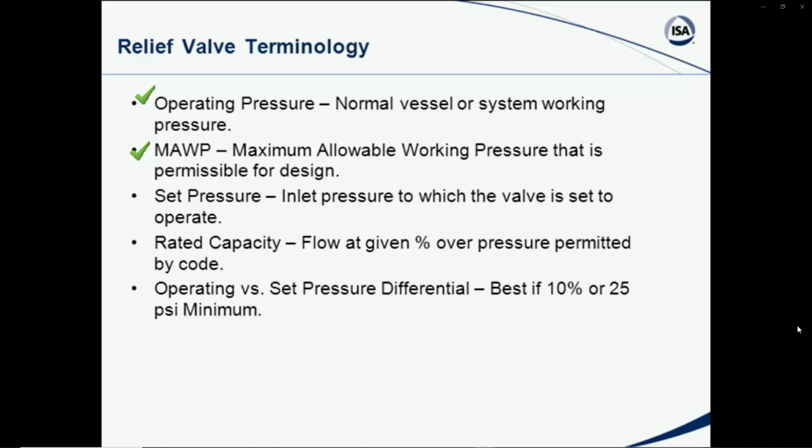The set pressure is the inlet pressure to which our safety valve is set to operate. That's the base pressure, the point where we have to start protecting or relieving. But there are some other terminologies involved also, like the rated capacity.